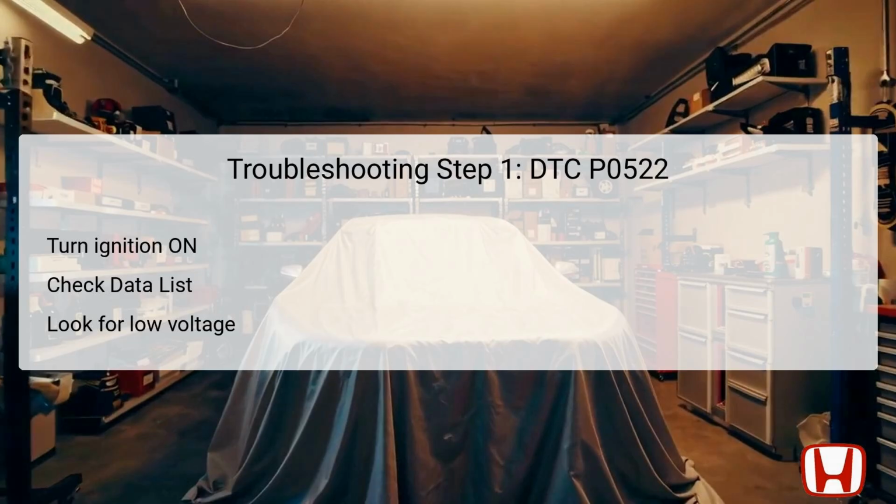However, if the voltage reading is higher than expected, this could indicate an intermittent failure, suggesting that the system might be operating correctly at that moment. In such cases, it is advisable to inspect for poor connections or loose terminals associated with the rocker arm oil pressure sensor and the PCM to ensure there are no disruptions in communication.